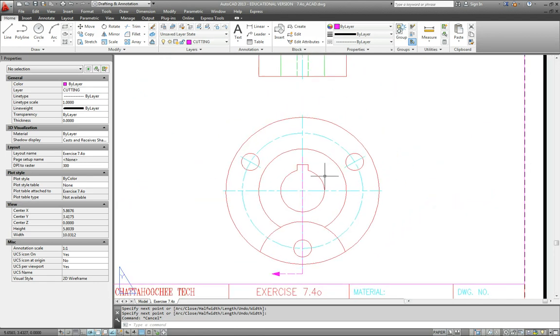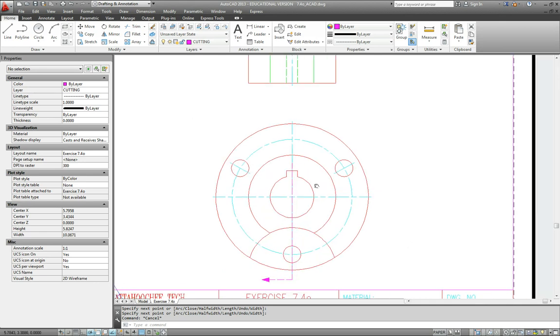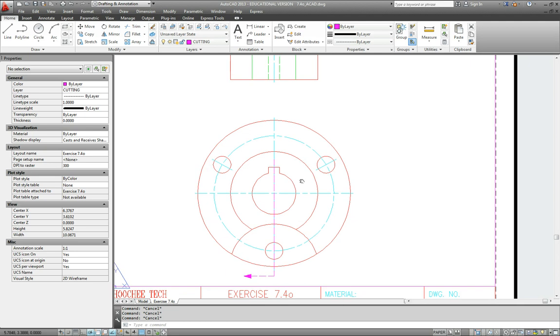Okay, now I have to end that line because I have to do something. Well, I could actually do it with the arc from here to here and stay in the polyline command, but I think that would be harder than it's worth. So for the portion of the cutting plane line that comes through here, I'll just start off at the center, go through, and I'll left click here, and I'll go in that direction to approximately here, then redefine my width, 0.1, ending width is 0, keep pulling in that direction, and 0.175 arrowhead length. And then finally I want to draw a circle.